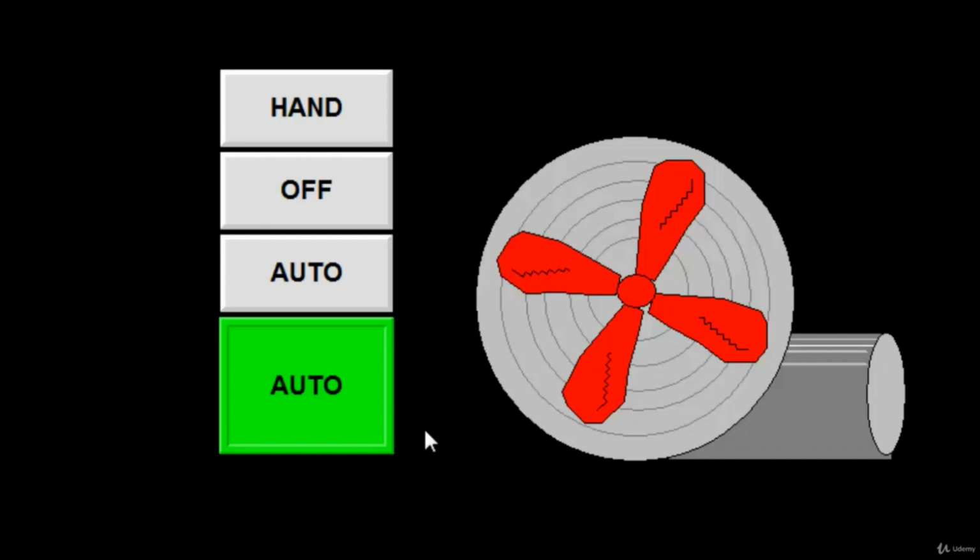And it is that simple to set up a basic HMI program. You define the tags, define the communication, drop in your controls, and it's as easy as 1, 2, 3. Obviously, a real HMI program for a live project will have a lot more controls, a lot more displays, a lot more graphics, maybe even some custom graphics and things like that. But really, it's all just more of the same. It's the same basic concepts multiplied several times over. If you can make a small HMI like this, making a larger one is only a matter of a little more creativity and a lot more time.